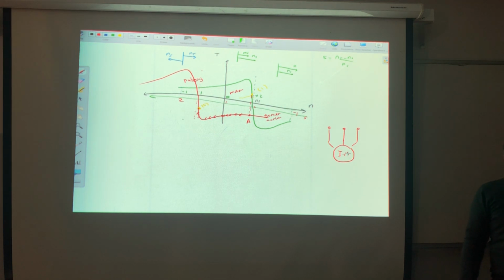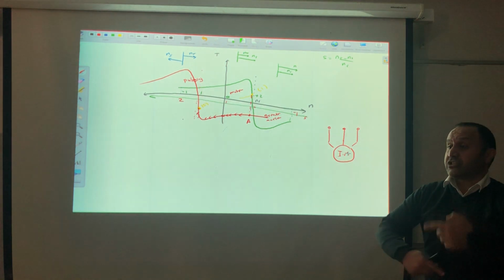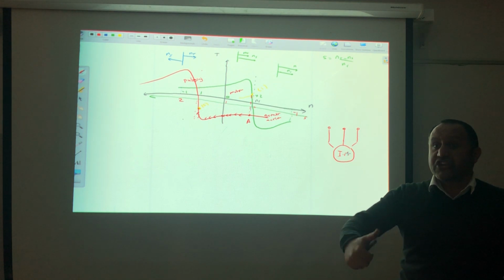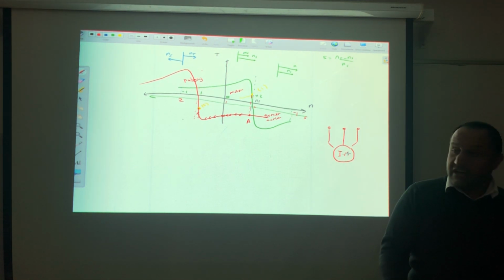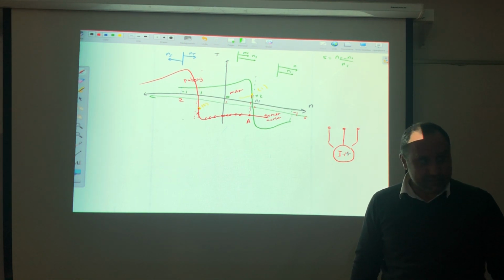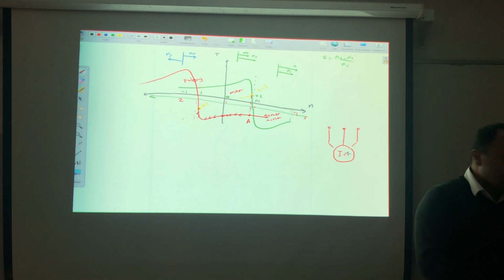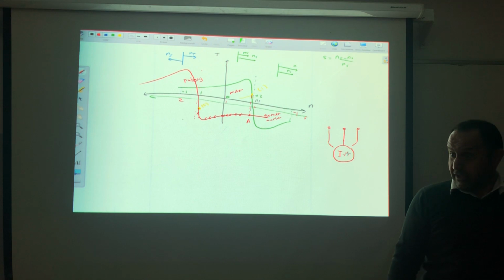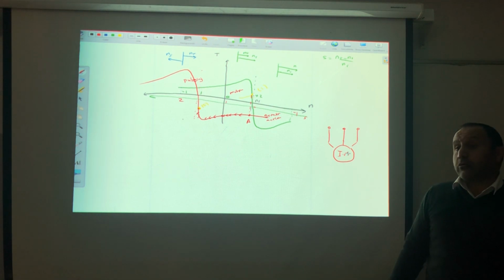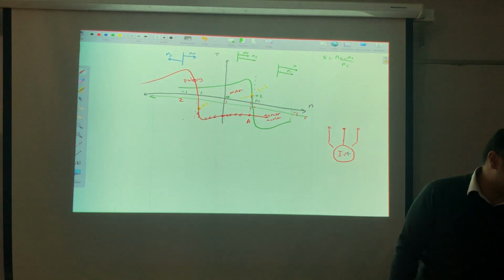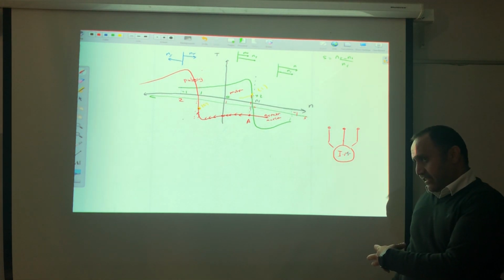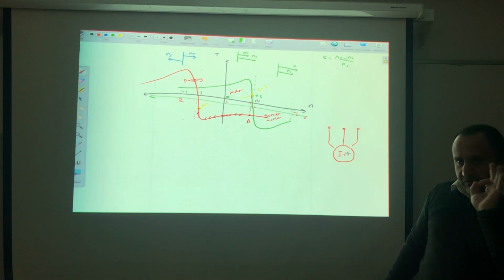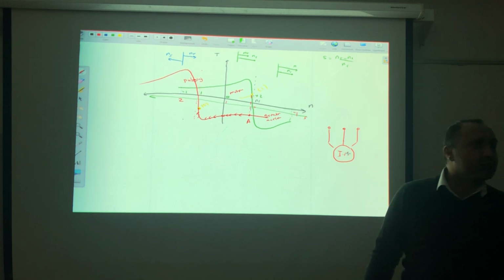Then what will I do? Remember, what makes the induction machine rotate? The alternating flux. So if I make a stationary flux on the stator, then the rotor will also have stationary flux. Then the north will catch the south, and the south will catch the north, and they stay together forever. They are stationary. Good. So how to generate stationary flux? By imposing a DC. But remember, I have an AC circuit here, so I will use a small DC. I will engage a small voltage such that a rated current will flow.